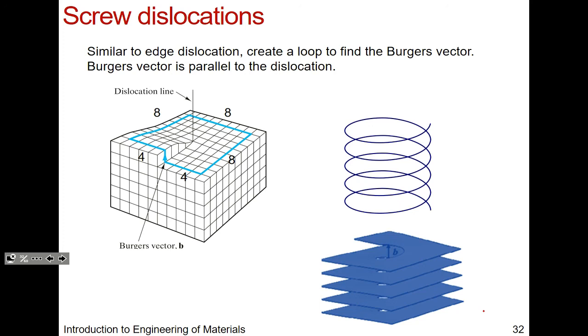But let's say you have now a screw dislocation. So what can happen is you have an extra half plane, but it goes like this, sort of like one of those parking structures or a slinky that you can think about, right? It starts on one plane and it ends on another plane. Your dislocation just keeps on going. That's another type of dislocation.